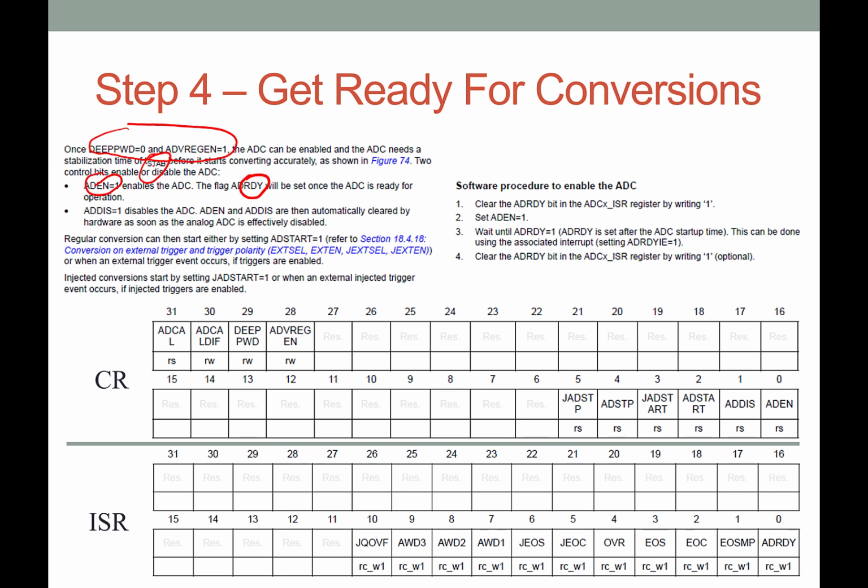So we've talked about all that. It talks about looking at this interrupt service routine register, which we can do, but we're not really doing that part. The main thing that we have to do is look at this, for us, the end of conversion flag. If you're using injected channels, you would need to look at this one. And so here's that ADRDY, so that's the bit that will tell you whether or not the AD converter is ready to go.